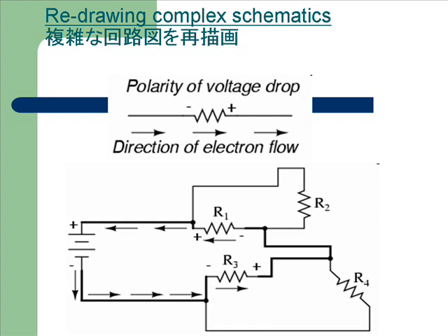When tracing this direction, I will mark each resistor with the polarity of negative on the entering side and positive on the exiting side, for that is how the actual polarity will be as electrons enter and exit a resistor. Any components encountered along this short loop are drawn vertically in order.